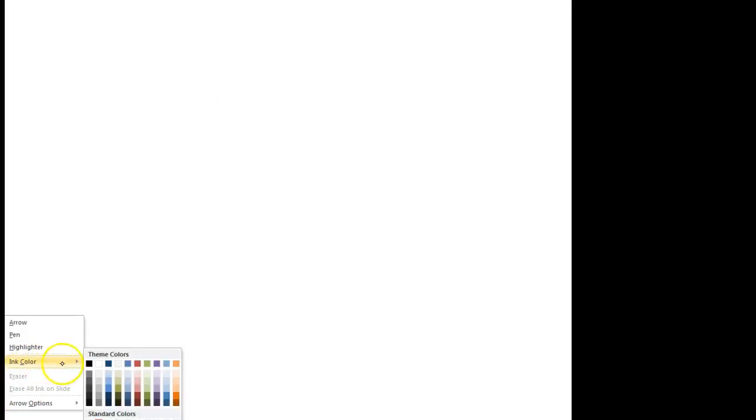So let's say I'm going to shift this number right here. How many bits are we doing? 7 bits. Okay, and let's say in my file that I'm shifting in, I have a 1 there. And then sitting right here is the unload bit. So I'm going to shift it once. What's going to happen? This is going to go into the unload bit, right? This is gone. This bit right here will come right there.